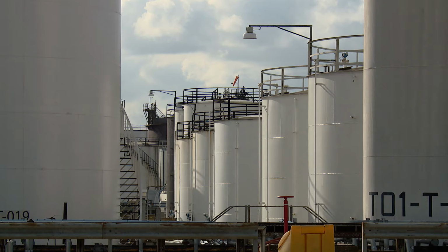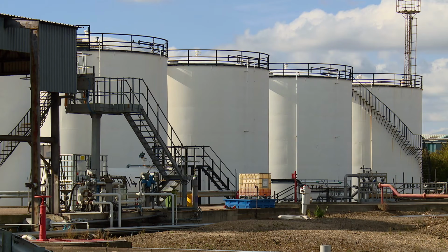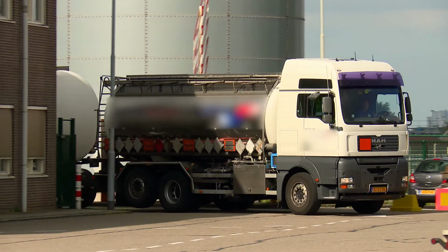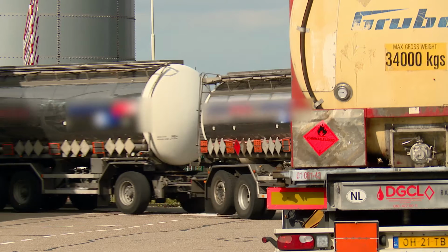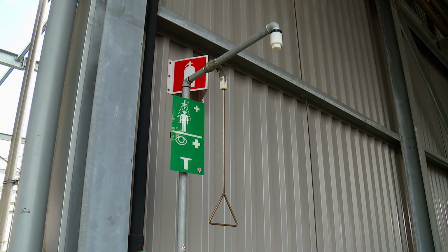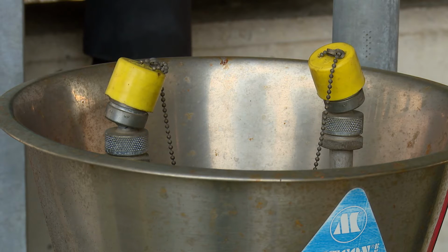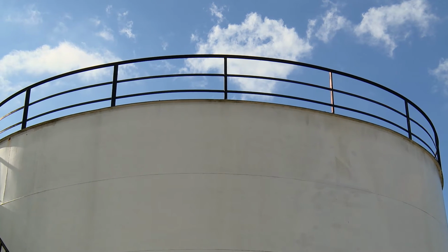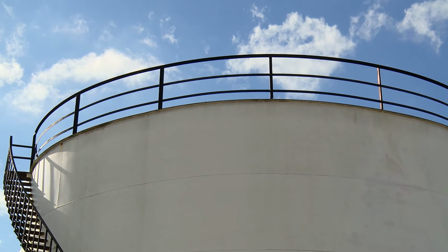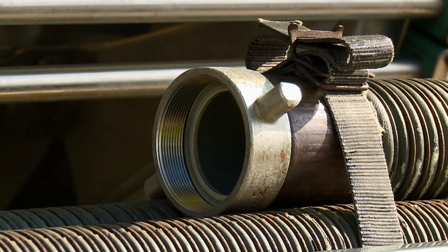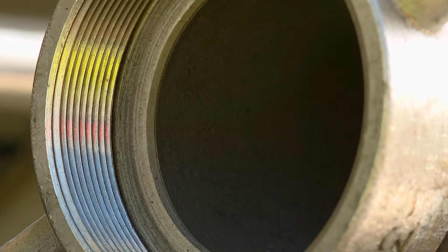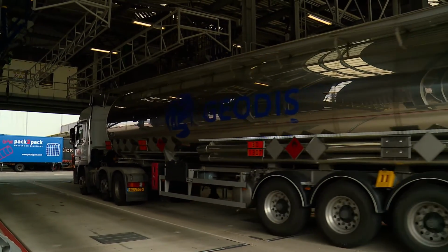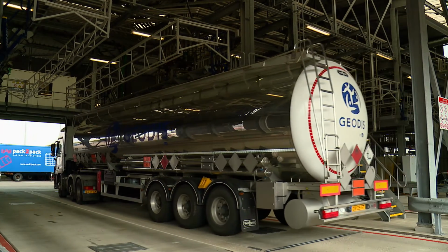Before arranging bulk discharge of any material at an unfamiliar site or storage tank, pre-delivery inspection is essential. This is to ensure that the vehicle being used is suitable for safe access to the site and storage area. Health and safety procedures on site meet the standards required, for example, eye wash stations and firefighting measures. The tank receiving the product is well maintained, is in suitable condition and of the right materials of construction to be compatible with the product being delivered. The vehicle discharge hoses carry the same size connections, and the driver will always, at their own discretion, have the final say as to whether a delivery is safe to proceed.